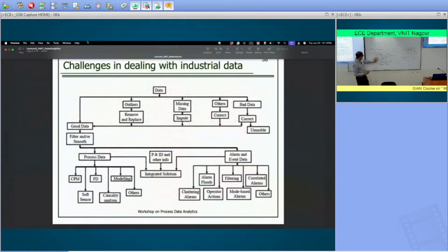The third problem, or a third way of estimating this unknown y bar t star, is to use not only past values of y, but also future values of y. So let's say you finish your experiment. You have all values of y from time 0 to time capital T, and you want to go back and get a better estimate of this. Now you have not only the past values, but also the future values. If you include all of those measurements, you'll get, hopefully, a far better estimate of epsilon, the noise, and therefore a better estimate of the true value of this measurement, right?